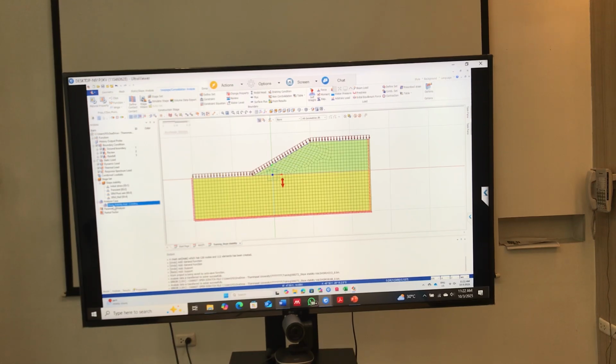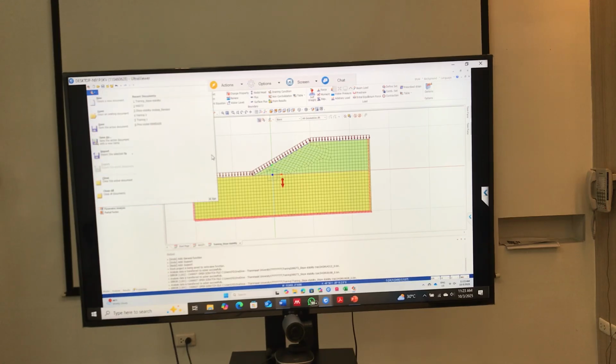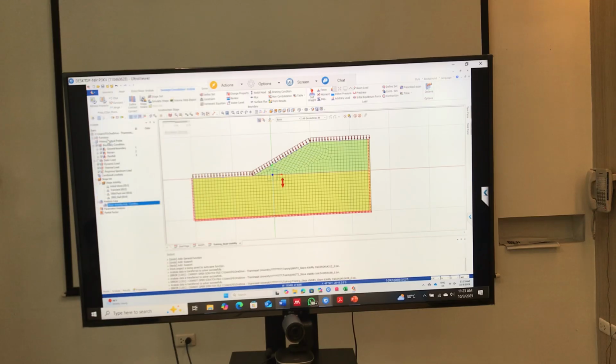Then we run now. Not working, still the same. Analysis data is transferred, solve successful, error: cannot open scratch file. OneDrive. Is it about the location where we are saving it?